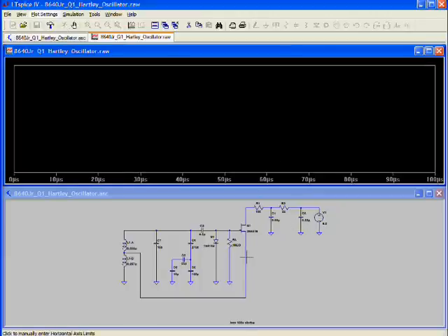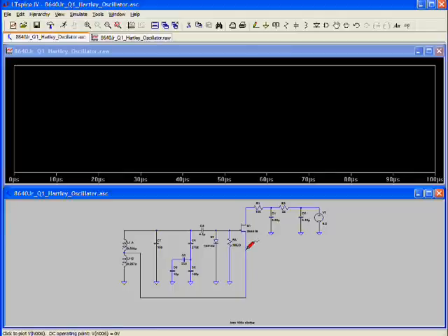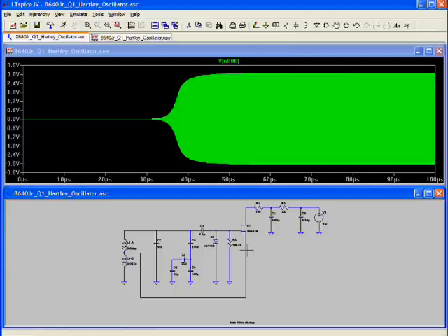And there, it's finished, and we can then probe and we see, okay, our oscillator is actually starting to run. About 30 microseconds in, it finally gets stable enough to begin oscillating and stay stable. So that's what you have to do for the startup thing.